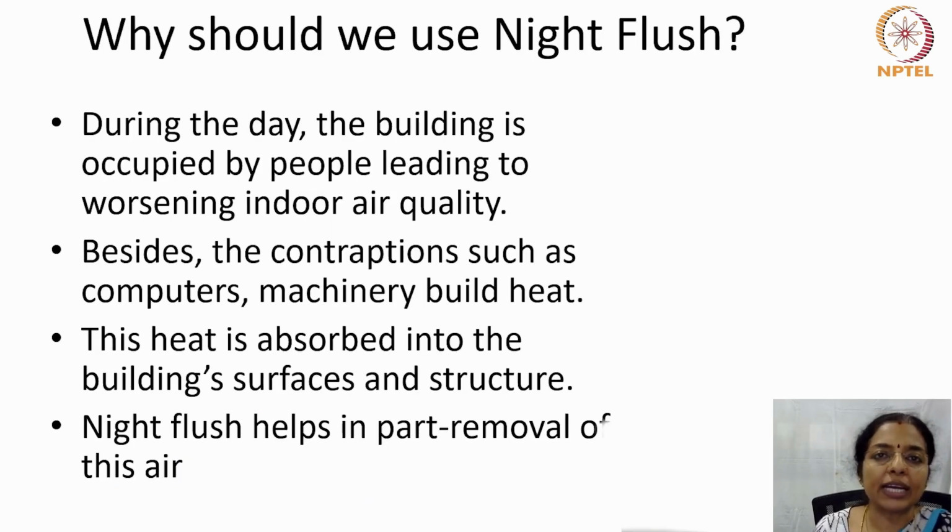Why should we use night flush? This is important. During the day, the building is occupied by people, which leads to worsening indoor air quality. The indoor air quality becomes poor because of a buildup of carbon dioxide and carbon monoxide because of breathing. Besides, there are contraptions such as computers and machinery, which build up heat. This heat is absorbed into the building's surfaces and structure. Night flush helps to partly remove this air.